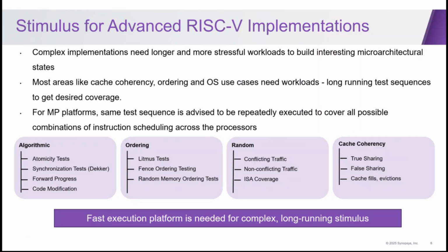For advanced RISC-V, to verify that, only cover all the instructions is not enough. Only cover the instructions using different registers in your instruction is not enough. Only cover this instruction, load instruction, followed by another instruction is not enough. If you want to verify the complex implementation like the Xiangshan product, you need to really run a lot of long tests to cover the scenarios, cover the microarchitecture design.